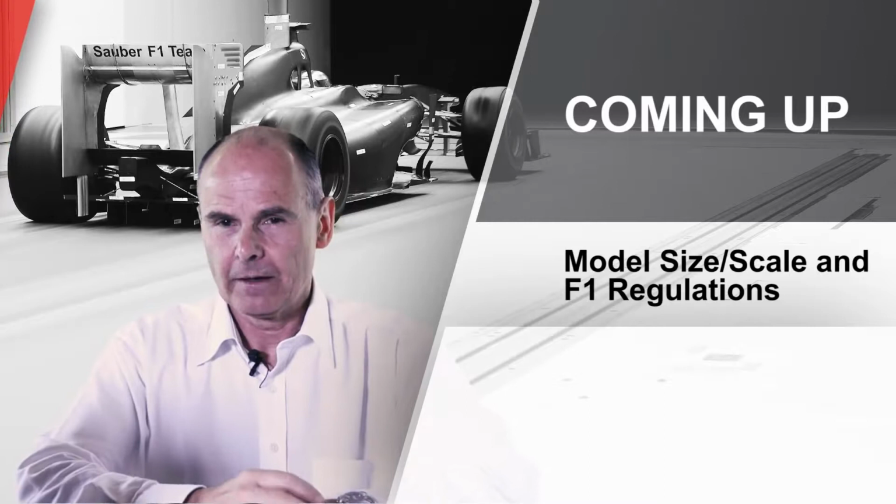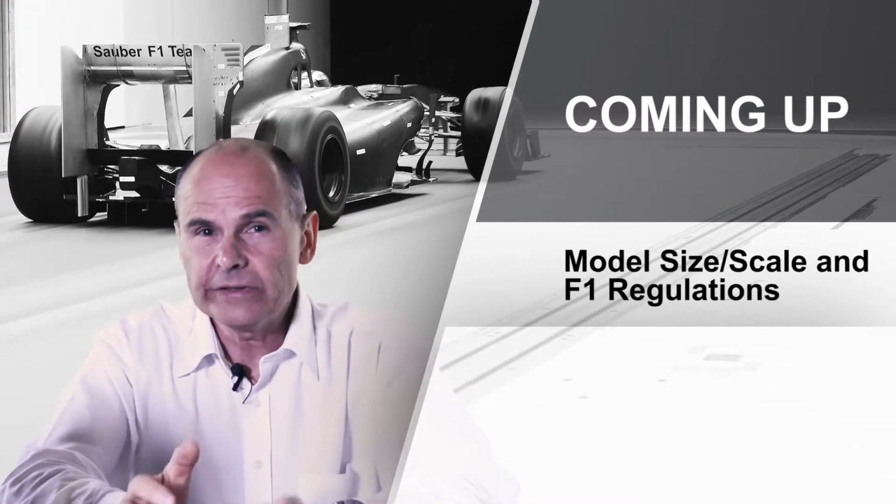Often when you see pictures of wind tunnel testing, you will see a man with a smoke wand and smoke blowing over the model to look at the nice airflow lines. So you might see a rake of several smoke wands creating a bit of smoke that blows over your test model and allows you to have a look at the airflow. These are useful, but as you gain more and more experience of airflow, they're useful for looking at, if you like, macroscopic overall airflow. We use that technology today for real aerodynamic research so rarely that we don't even own a smoke generator for human eye visualization of the smoke.